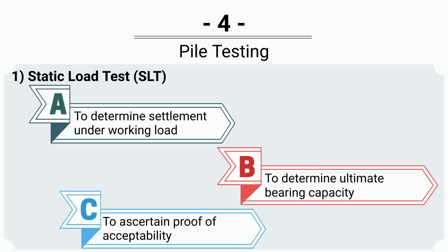Fourth, pile testing. Static load test. The objectives of this test are: first, to determine settlement under working load. Second, to determine ultimate bearing capacity. And third, to ascertain proof of acceptability.